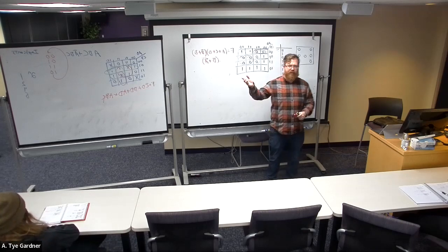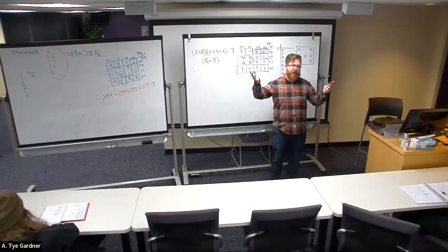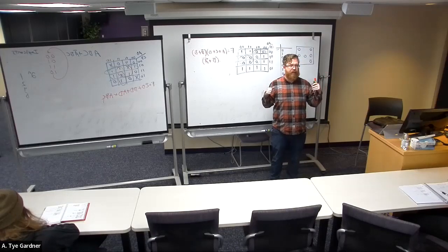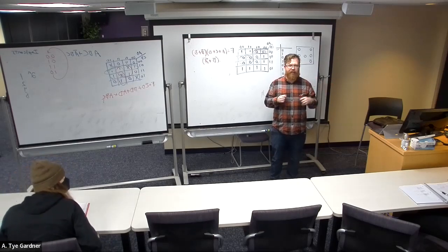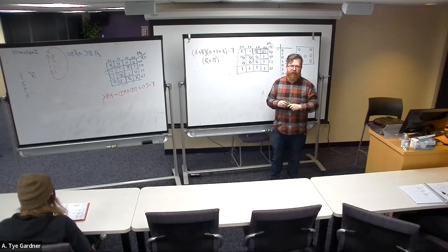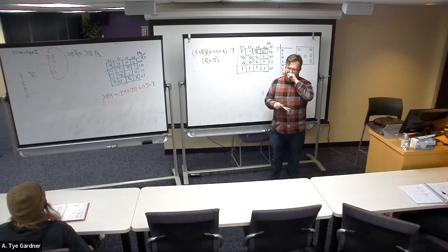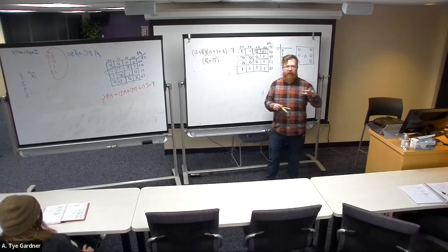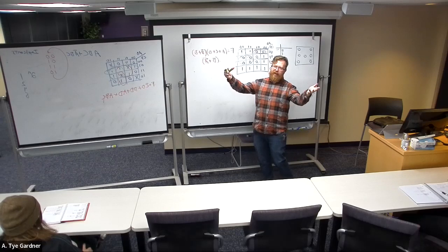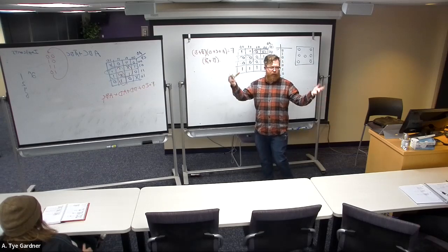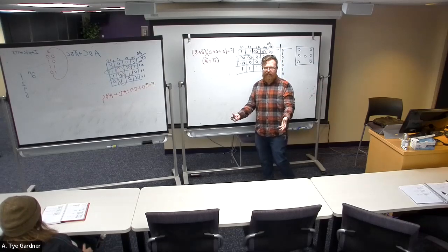That's don't cares, that's zeros. Don't cares occur anytime something can't happen, shouldn't happen, or doesn't make any sense. Like, why is that a thing? So those are don't cares. The shouldn't happen is a little bit iffy, because what I mean is you have a scenario where if it's going to happen, but if it does, I don't really care what happens. That's what don't care says. I don't really care what my output does in this scenario.